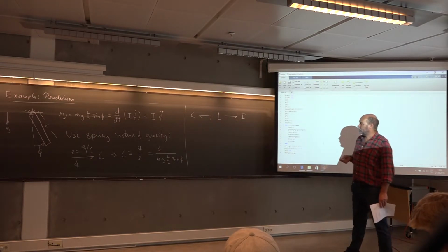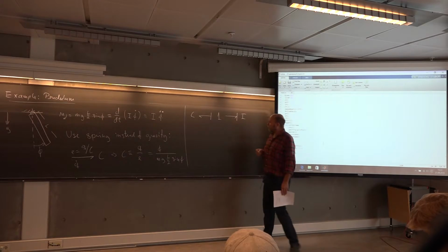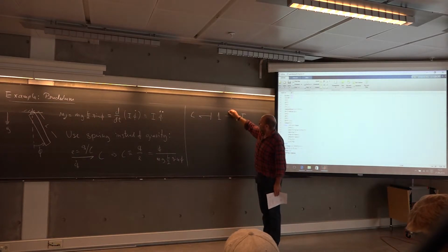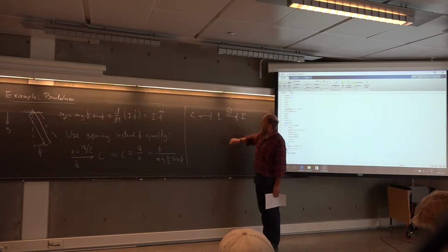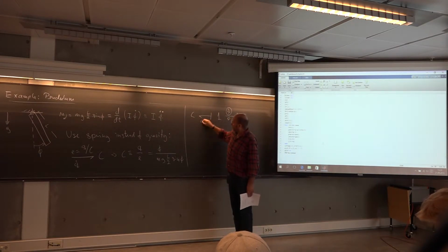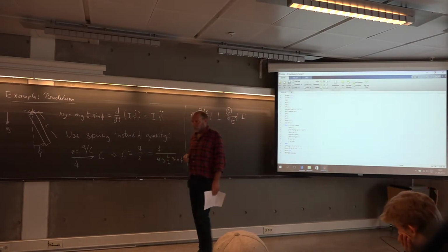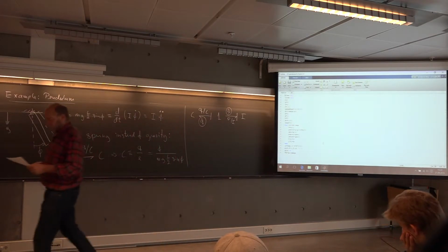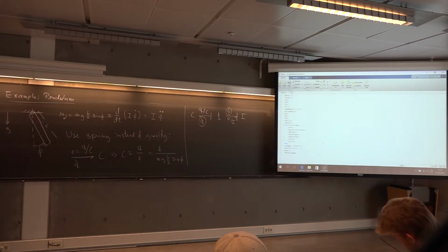So now we can write our differential equations directly. Here you will have a P dot with a circle, and here P over I. While on this side you have Q dot, circle, and then Q over C. So there we have our bond graph now completely annotated.